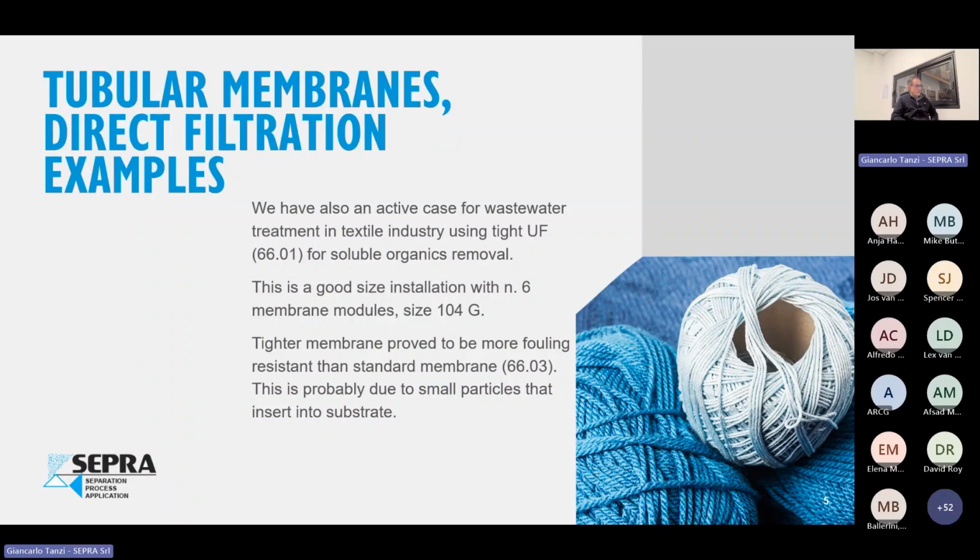One is related to a wastewater application in a synthetic textile production line. I'm mentioning this not because of repeatability. This is a very special case, but because it was an opportunity to switch from the more standard PVDF loose UF membrane, that is a standard in biological application.